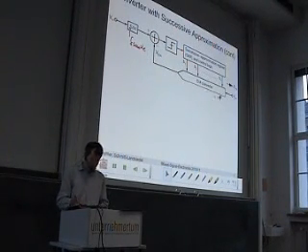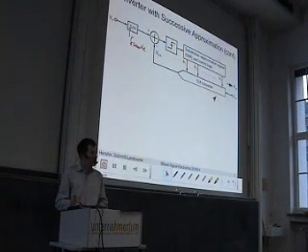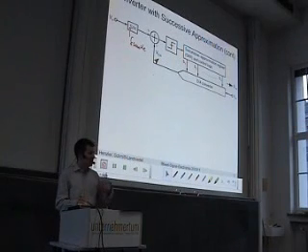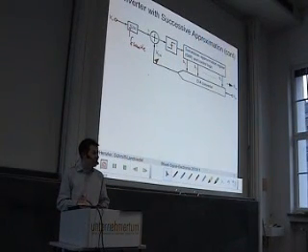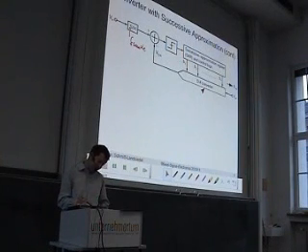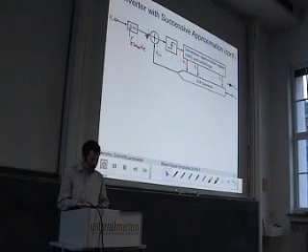You can see here on the right hand side we have a D to A converter. And this D to A converter generates the voltage VDA, which is the internal signal that is always compared to the sampled input signal. You can now also understand why we call this VDA, because it is controlled by a D to A converter. So at the beginning we have here the 0, we compare it to the input signal by subtracting the two signals and feeding them to a comparator.